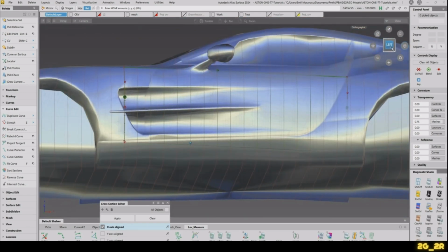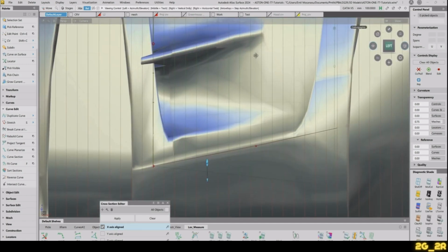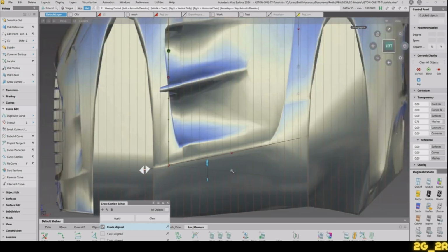Let's get the curve in first. So get a degree 1 curve. And you see it's too stiff. So turn it into degree 2. And I'll push the CV a little bit back in, a little bit up, so it resembles that curve more. To get that in, we can squeeze a view and see that this will work nicely. You can extend that curve a little bit, still working along there.